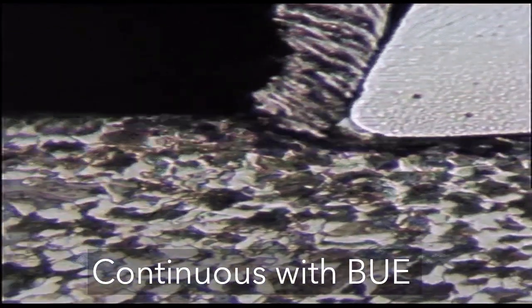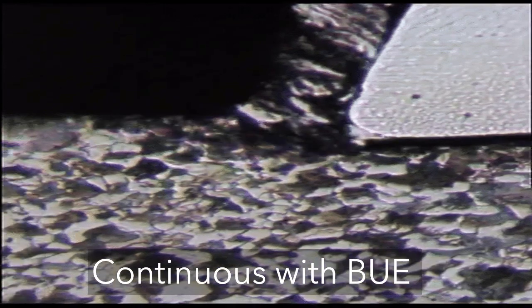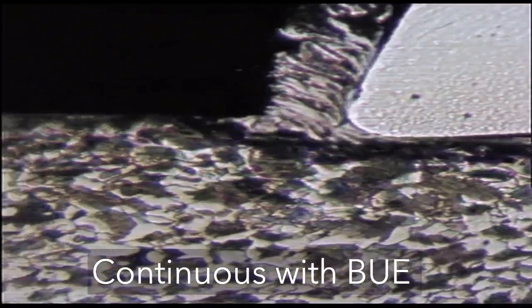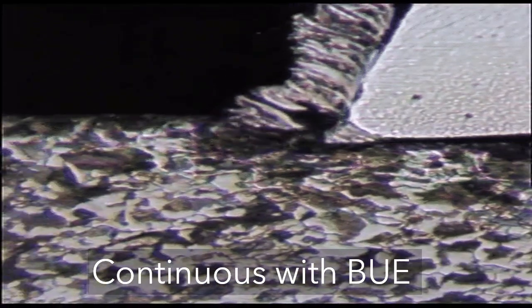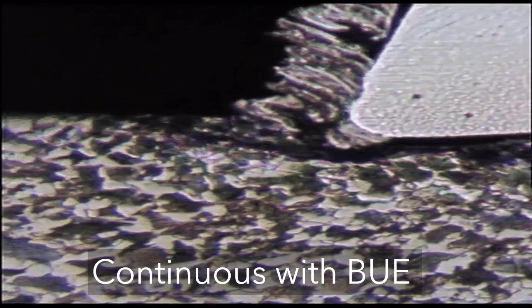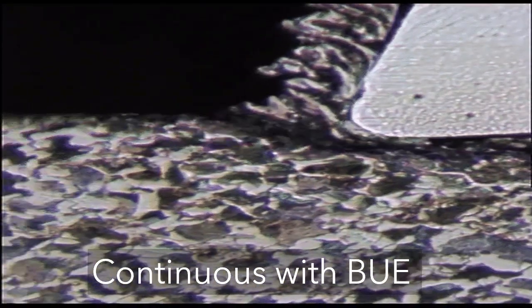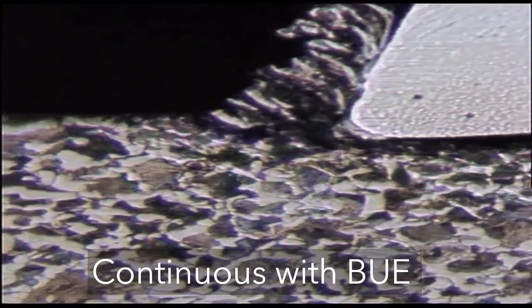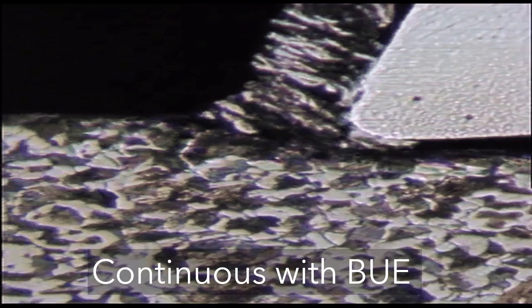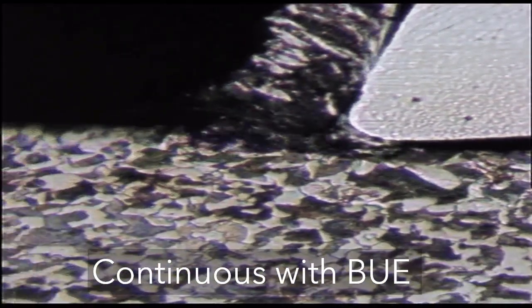Much of the detached built-up edge is carried away with the chip, sometimes taking a portion of the tool rake face with it, which reduces the life of the cutting tool. Portions of the detached built-up edge that are not carried off with the chip become embedded in the newly created work surface, and this causes the surface to become rough.